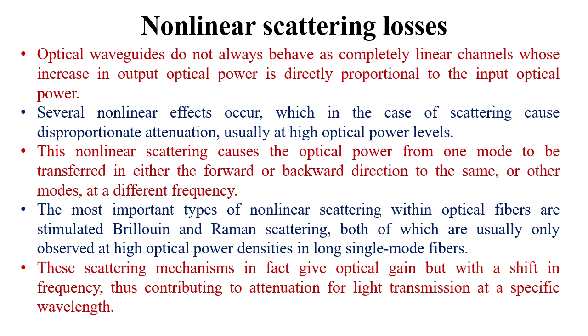Several nonlinear effects occur, which in the case of scattering cause disproportionate attenuation, usually at high optical power levels. This nonlinear scattering causes the optical power from one mode to be transferred in either the forward or backward direction to the same or other modes at different frequencies.